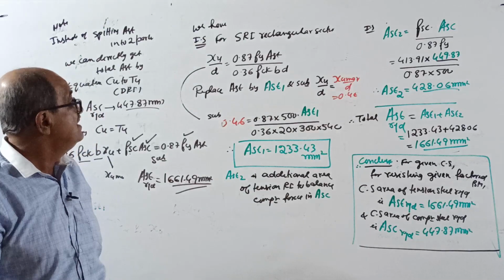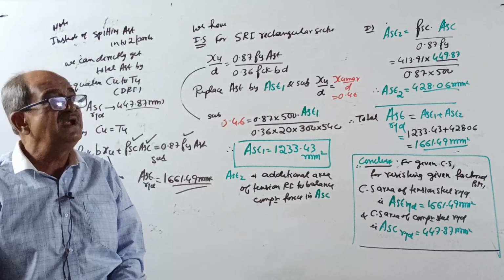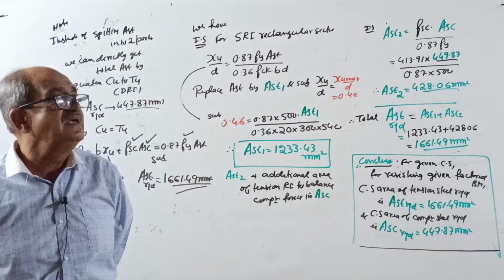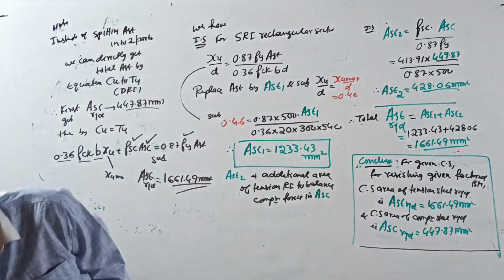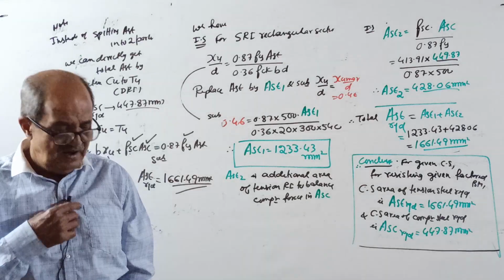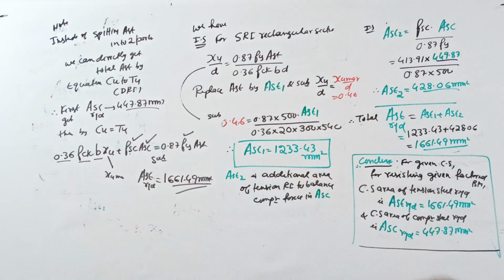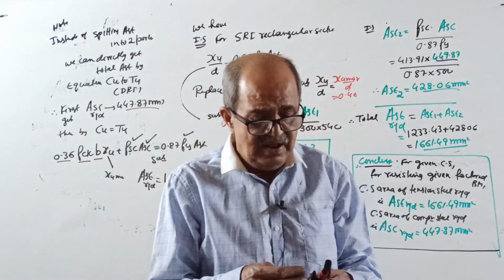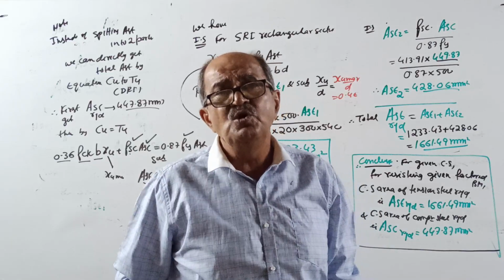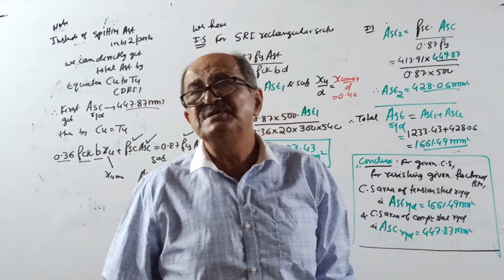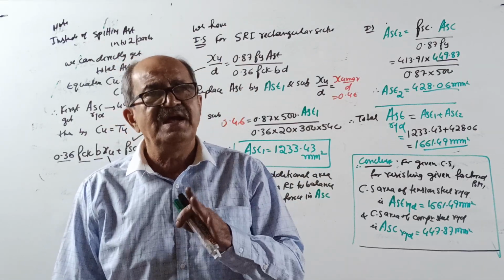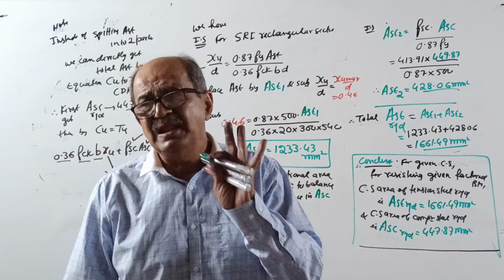Okay, now, the systematic way of calculating the required longitudinal reinforcement for both singly and doubly reinforced sections. Singly means only AST, doubly means AST and ASC. Everything is over. Next I will go for design of shear reinforcement by the limit state method. After that, last, I will consider analysis of the T section. It is very important, and many get confused in that, especially when the neutral axis comes in the web, where two different types are there. When I consider the cases, I will do it systematically.